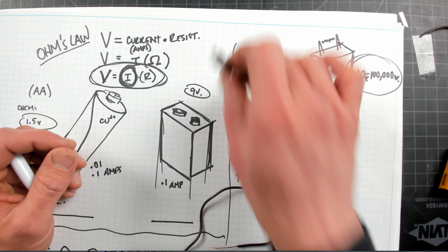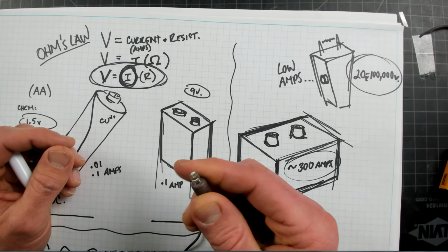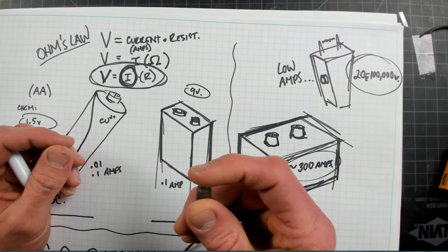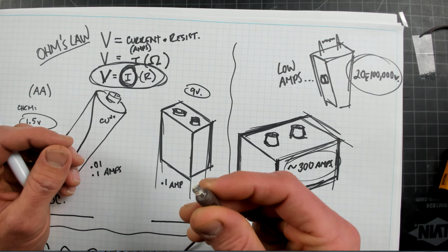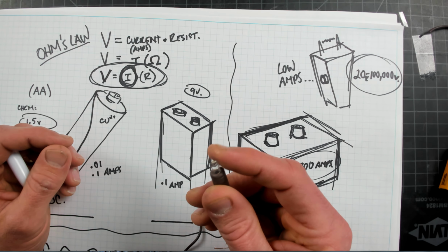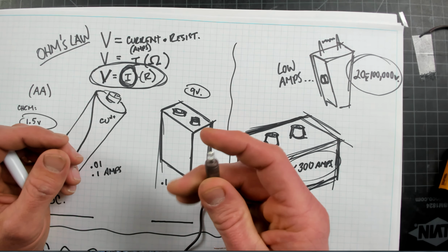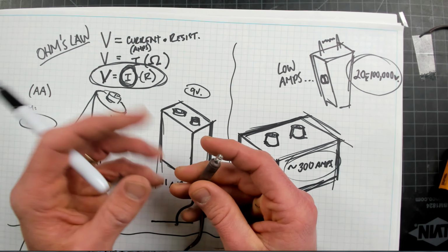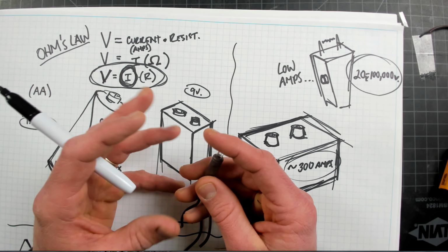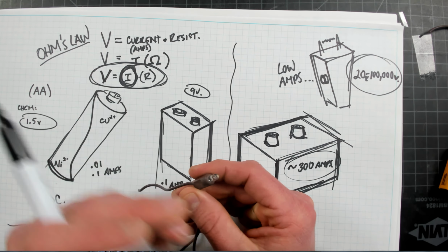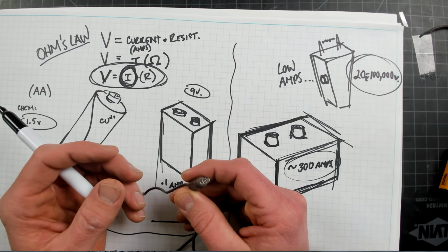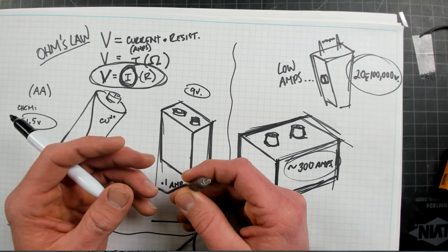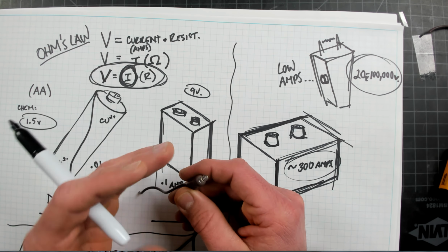But just note this: when we're doing this, you can't use red or yellow LEDs. Red and yellow LEDs will not work out, or orange, because I know that red, yellow, and orange require less voltage. And so anytime I've done this with lights, white's fine, blue, green, purple, pink, all those colors of LEDs or incandescent bulbs will be fine.